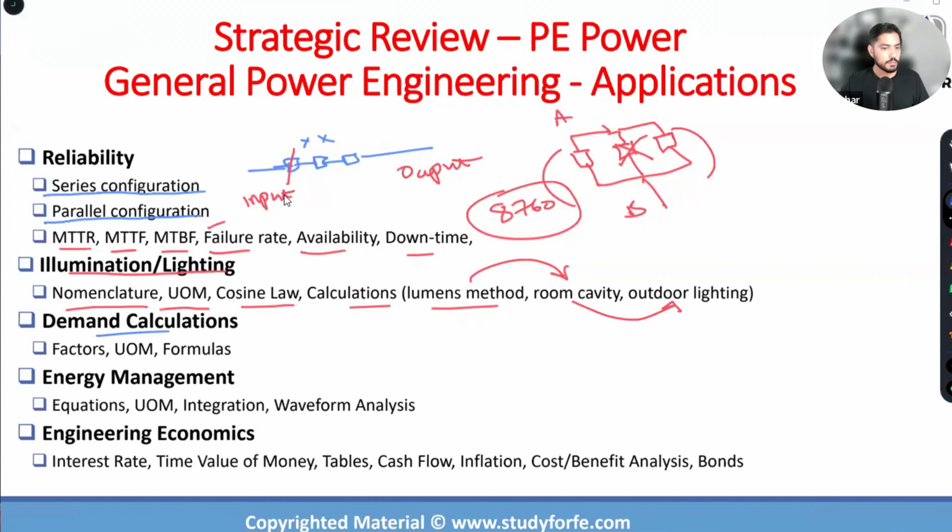We had good discussion on demand calculations in the on-demand course, in the live training, during the office hours. So the way that it is laid out, it takes about 1 page of real estate in the reference handbook. Okay. And when it comes to demand calculations, what we need to keep track of is the terminology. All the words, maximum demand, coincident maximum demand, connected load, total load. So you need to make a distinction between all of these factors, right? Otherwise, it is so easy to lay the landmines for you.